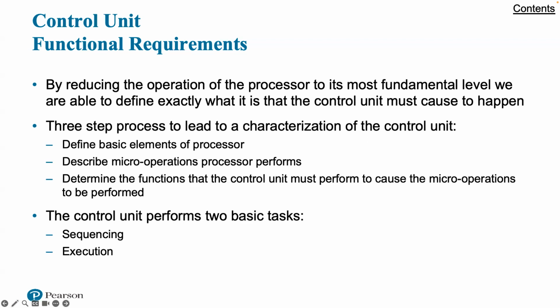The execution of a program consists of operations involving these processor elements. As we have seen, these operations consist of a sequence of microoperations. Upon review of section 19.1, the reader should see that all microoperations fall into one of the following categories: transfer data from one register to another, transfer data from a register to an external interface, for example, a system bus, transfer data from an external interface to a register, perform an arithmetic or logic operation using registers for input and outputs.